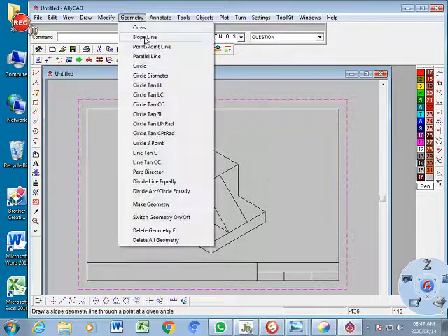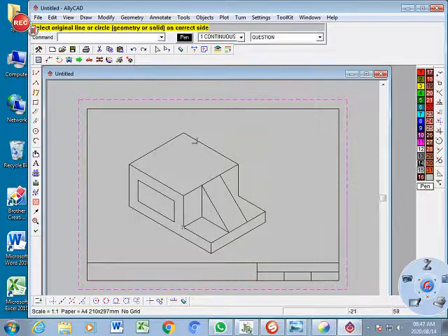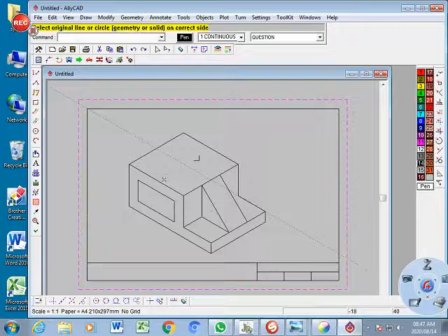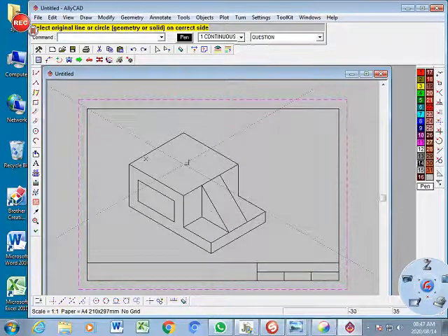So what I need to do is that 60 and that 60, so I'm going to create 30s and 30s. So parallel lines again, parallel lines, I say yes, because I want to measure. Click next to that line, I'm going to punch in 30, click, and I want a cross, so I'm going to enter next to this line here, and I'm going to click again for my cross there. There's my cross.